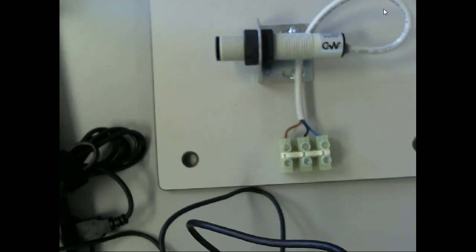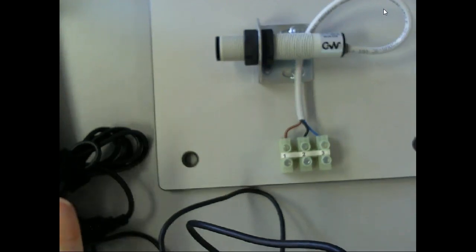So Mercedes has got a $50,000 car down there that they just put a fresh coat of paint on, and they want to sense when it's at a certain position. They're not going to use a limit switch. They're going to use some type of non-contact sensor, right? It might be what we call a through-beam.